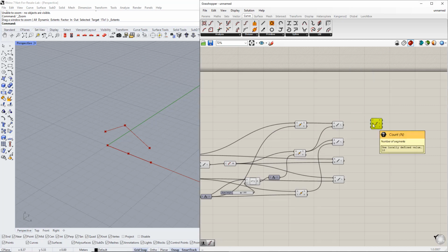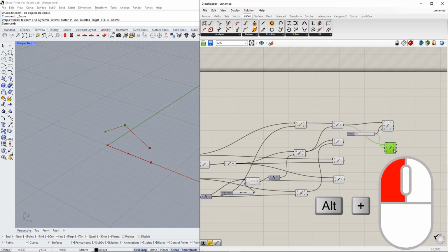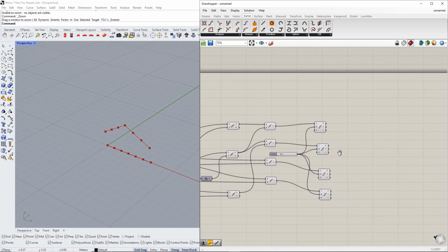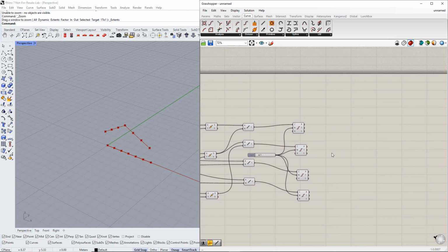By default, the value of the segment number is 10. We set up a new range, for example, from 1 to 15. We repeat this for other lines with the same number of segments. Now we create the verticals as well as the diagonals. We begin with the verticals.